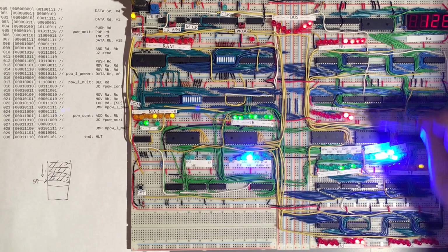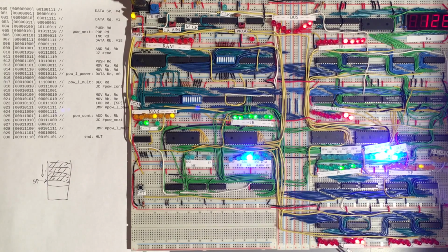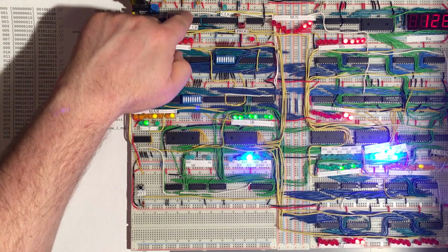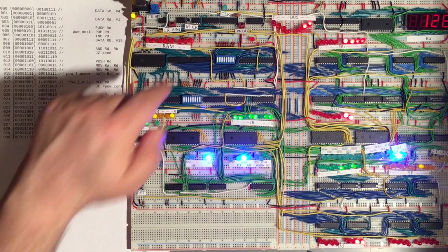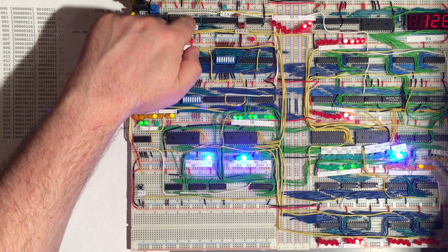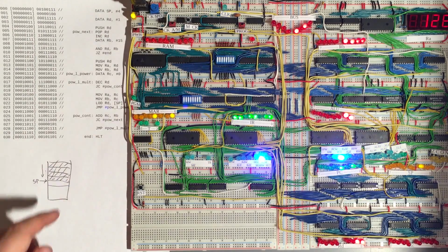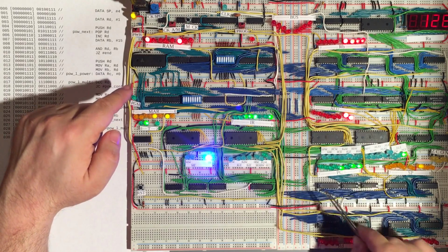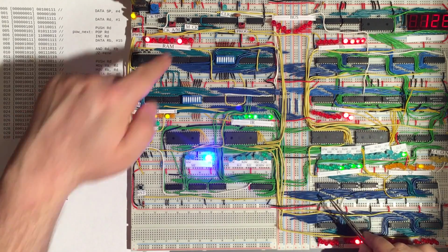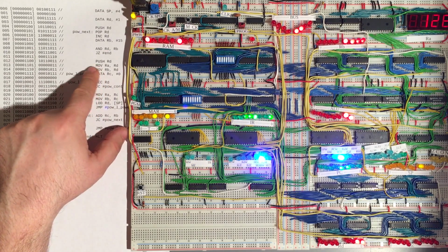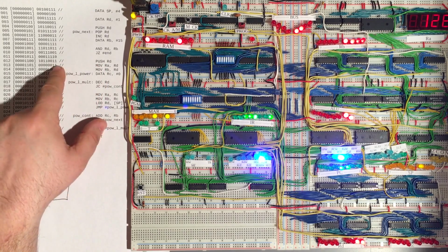But so okay, let's calculate this AND. So in this case, the result is going to be exactly the same. We'll have 0, 0, 1, 1, and so that will go into the ALU. That happens to already be there, but that's of course a coincidence. And so there it is, and then we'll write that back into the D register. And of course, doing that didn't provoke a 0 because this value is not 0, and so the next jump 0 instruction will not take hold. And so when we load that and put it in here, then we won't actually perform the jump. We'll simply be increasing the program counter to jump over this address here, and then come to the next instruction, which is the push instruction. And so that's the last instruction we'll have a look at.